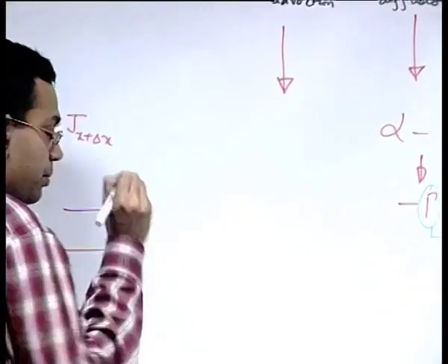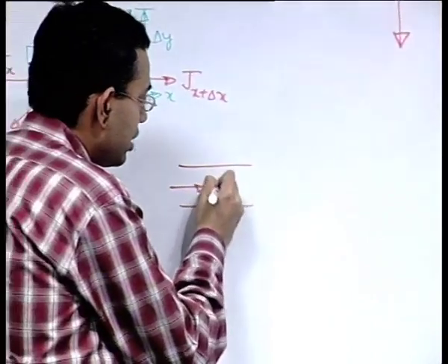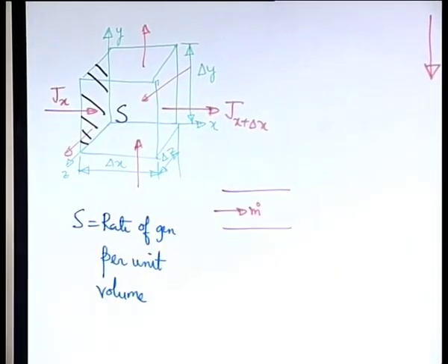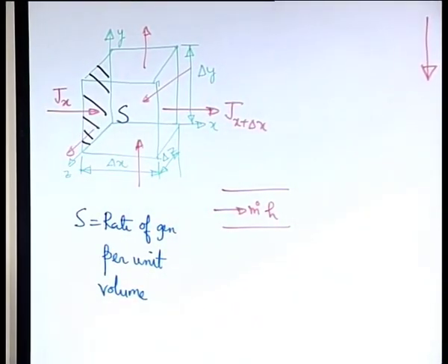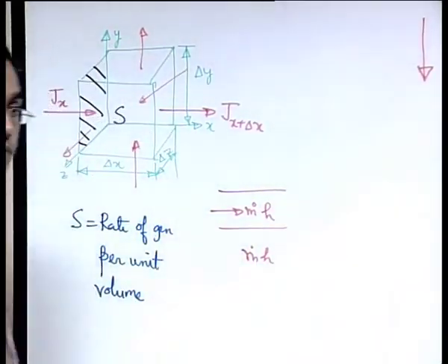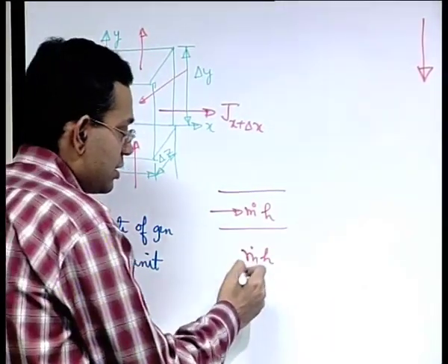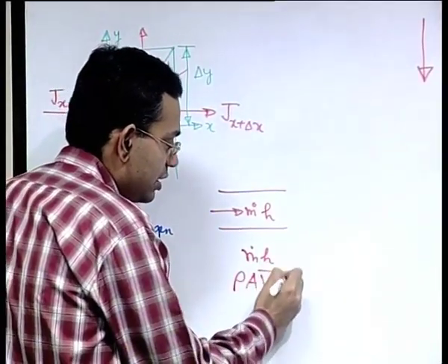Let us say that you have a pipe, and let us say that m dot is the mass flow rate across each section of the pipe, and let us say that H is the specific enthalpy. Then what is the rate of transport of thermal energy because of the mass flow? M dot into H, right. M dot is rho A into average velocity into H.